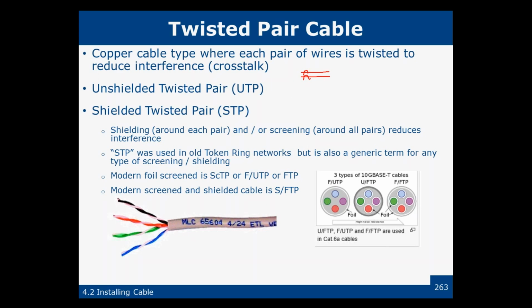What the twists do is to move the cables slightly out of phase, and this right here would be noise, and that's what we're worried about: crosstalk, interference, and noise. If they're not twisted, they're going to produce interference with each other. If we're twisted, we make a little bit of change, and the twists are all at different numbers of twists on each of the wires. When we look at this thing here, the pairs themselves, we have 4 pair. The pairs themselves are twisted, and inside the cable itself, there also are twists when we do those.